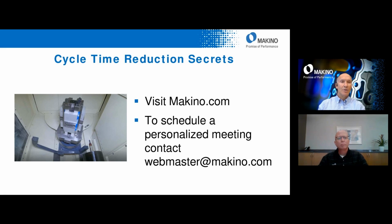The first one coming in is from Mitch. He's asking, does the machine generally come from the factory with M319? Yes. So 9001 M6. Every time the CNC program sees the M6, it executes macro program number 9001. And this is for moving to the ATC position, doing those things and getting ready for your tool change. So within the 9001, there is an M319. And that's a good place to put M319.